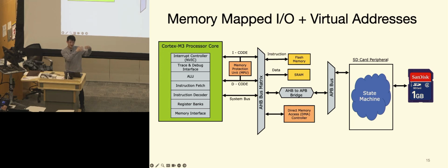If it matches for that address, it just takes that data into that buffer register and then pushes that data to the correct location on the SD card. So one state machine plus a couple of buffer registers will be able to give you full access to the entire 1 gigabyte worth of the SD card. Pretty clever, right?